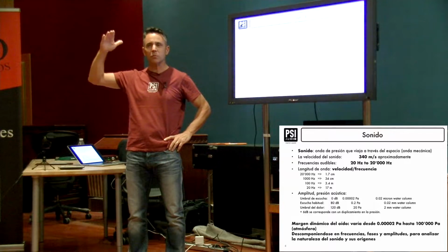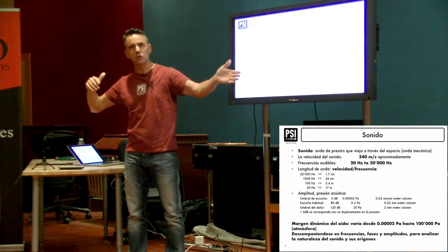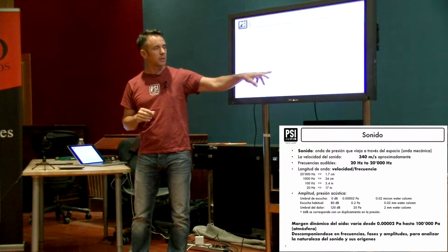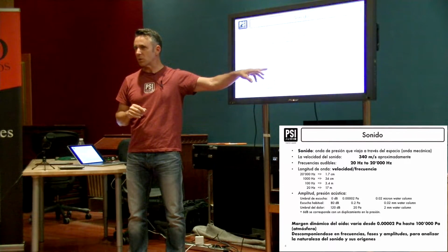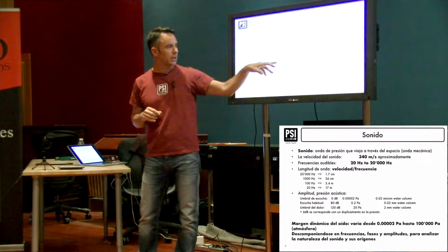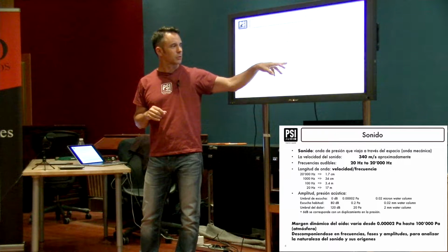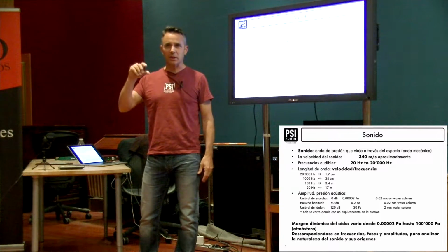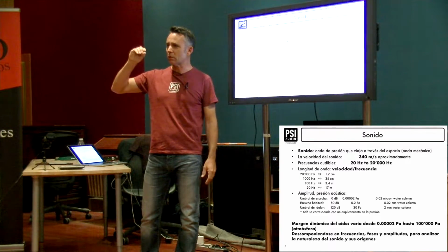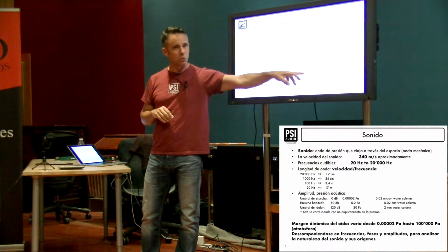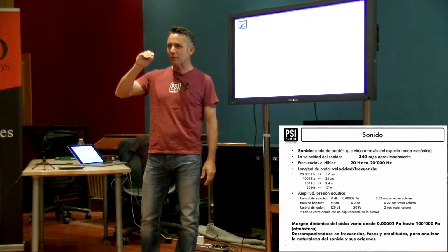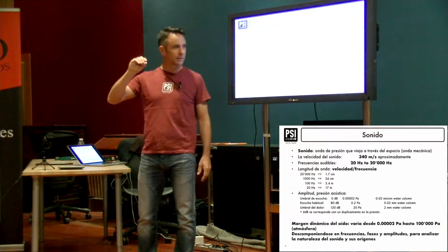It's nothing to do with atmospheric pressure or any pressure difference you get when you open a door. But we can hear from 0 dB to 120 dB, where we start not enjoying listening anymore because it's too loud. But 0 dB is 0.0002 Pascal, and Pascal is a really small element, and that corresponds in terms of water column to 0.02 microns of water column. So you're kind of at molecular type of width.